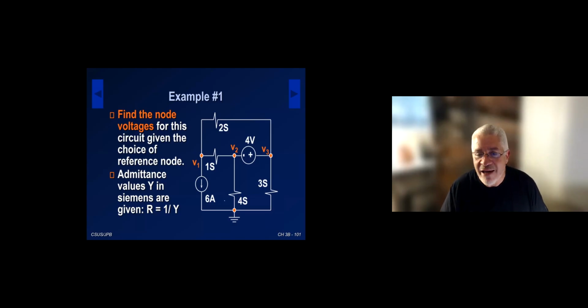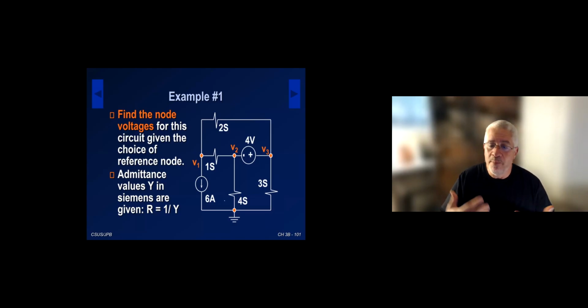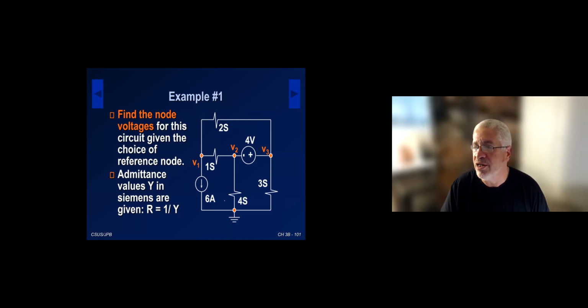The only thing that's left here, I haven't put current on my resistors. Now, keep in mind here, I'm giving you admittances. Anytime you see S for resistance, I'm giving you admittances just to make the calculation a little bit easier. So the admittance is given, the resistance is 1 over those values for each resistor, okay? And this particular problem is asking, let's find the node voltages.